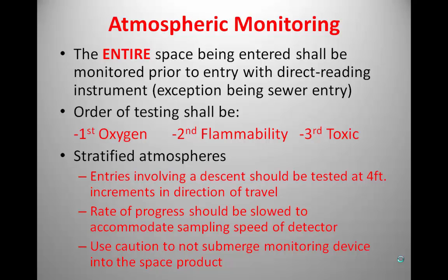And then lower it down the last little bit, and then get our final reading after 10 seconds. To help with this, we've actually marked our 10-foot tubes with black marks every 4 feet, so you don't have to guesstimate what 4 feet is. Also, use caution not to submerge the monitoring device into the space's product.